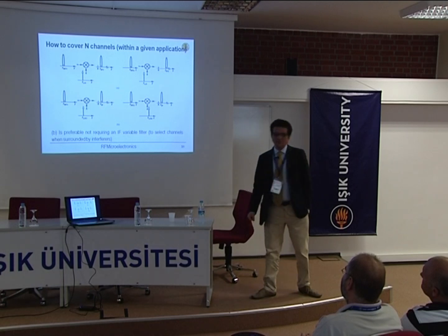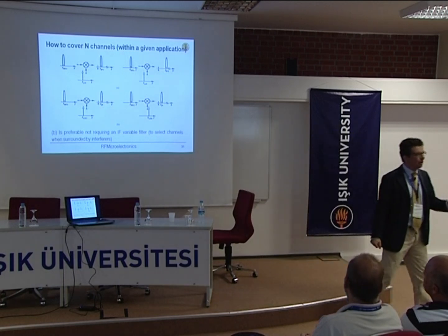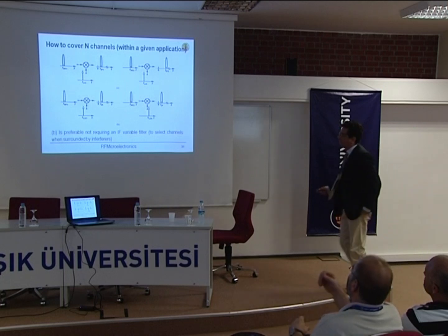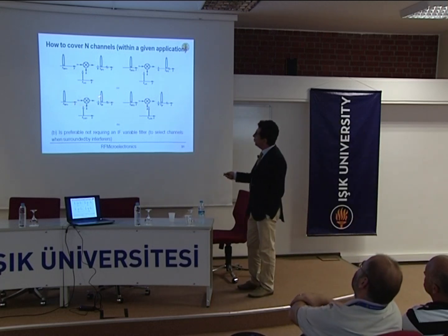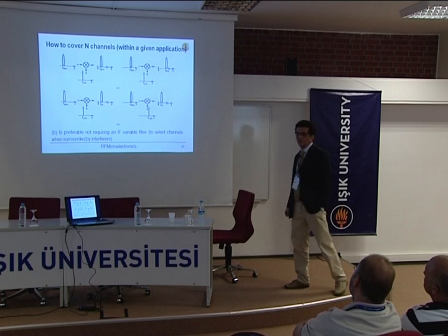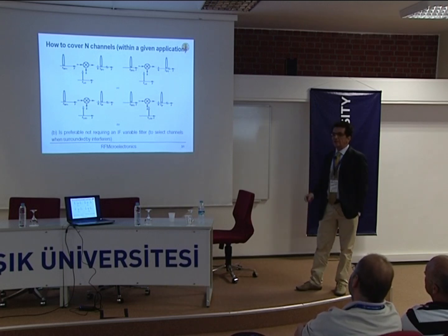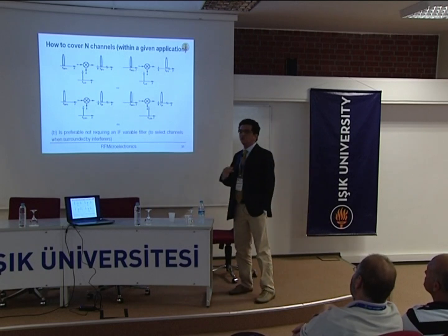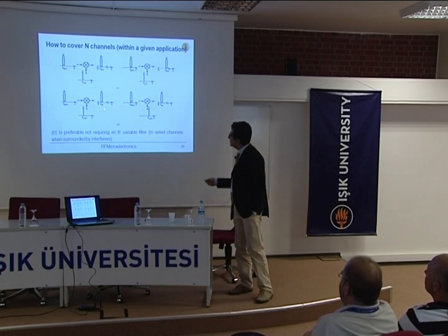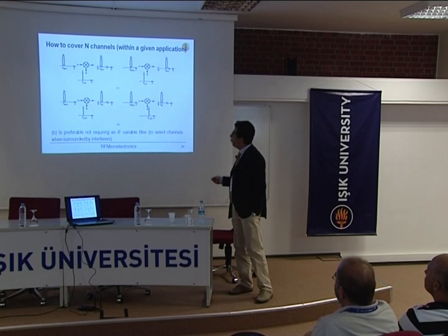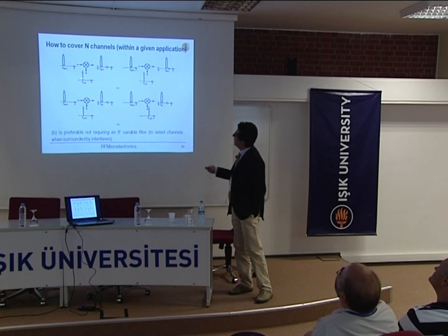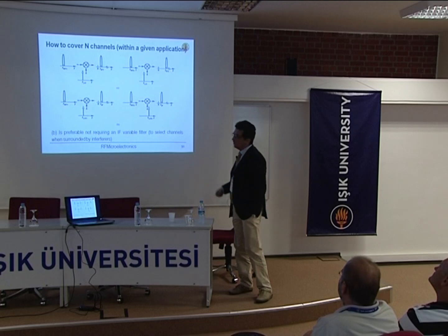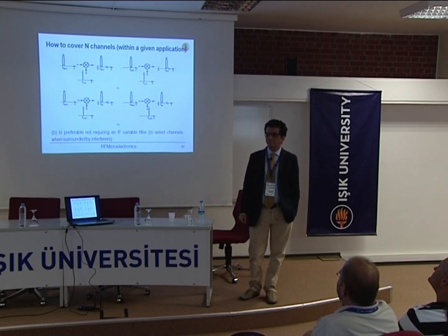So basically what the receiver does is tune the local oscillator in such a way that, whatever the RF frequency, it is always translated to the same IF. And it is at this IF that I concentrate my attention to design a good, selective filter, and select this channel over all the others. Whereas if I were carrying different frequencies, depending on the frequency at RF, the filter would be much tougher to do. Okay?